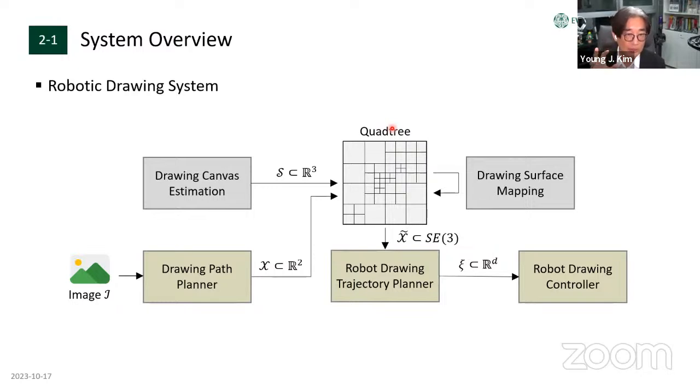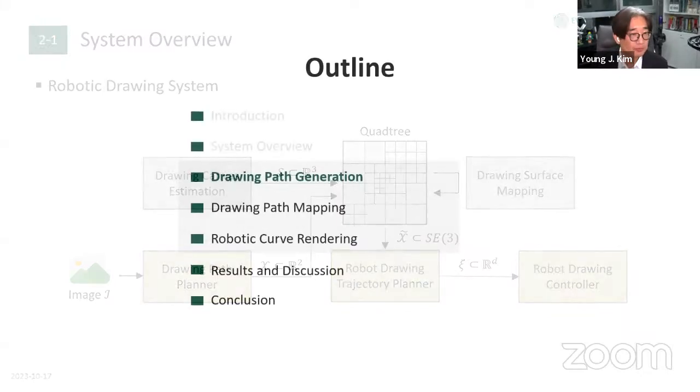And then the point sample geometry should be mapped to the final 3D surface. From this mapping, we find the corresponding pose of end effector locations. From those end effector locations, finally, we find the joint configuration of the robot to finally realize it. So we need all these steps, and we will go over them one by one, in a relatively quick manner from now on.